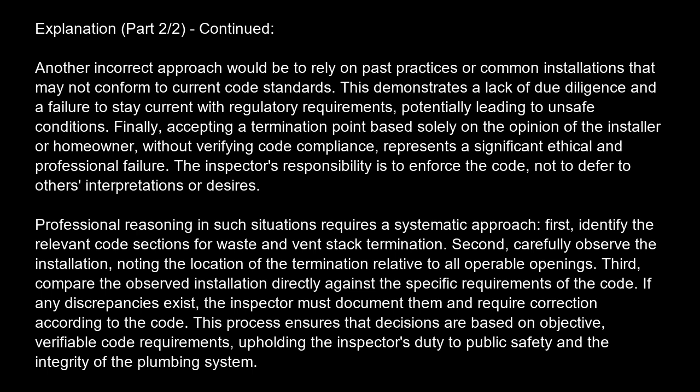Professional reasoning in such situations requires a systematic approach. First, identify the relevant code sections for waste and vent stack termination. Second, carefully observe the installation, noting the location of the termination relative to all operable openings. Third, compare the observed installation directly against the specific requirements of the code.